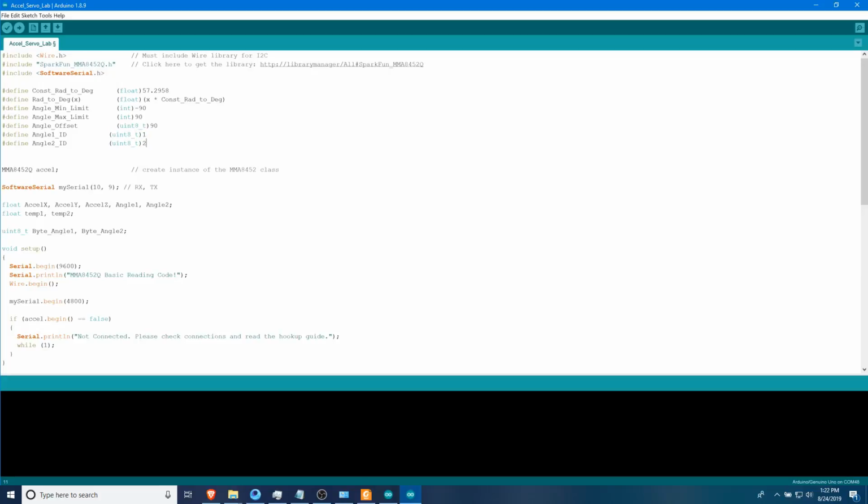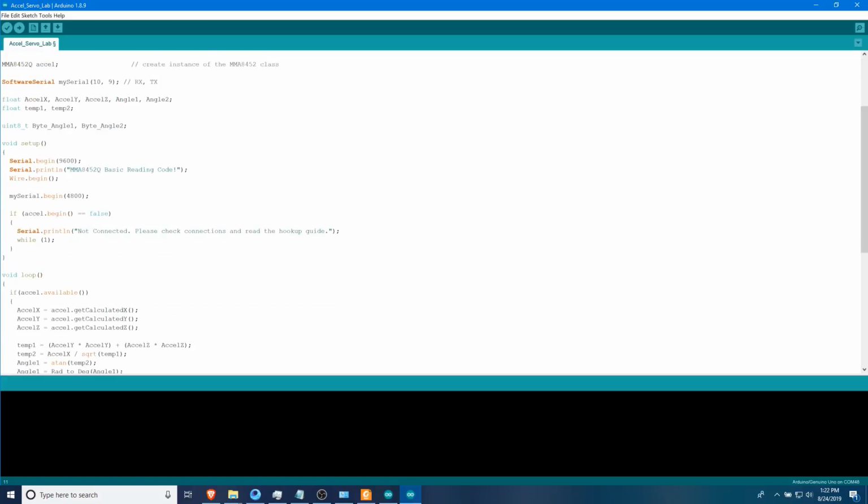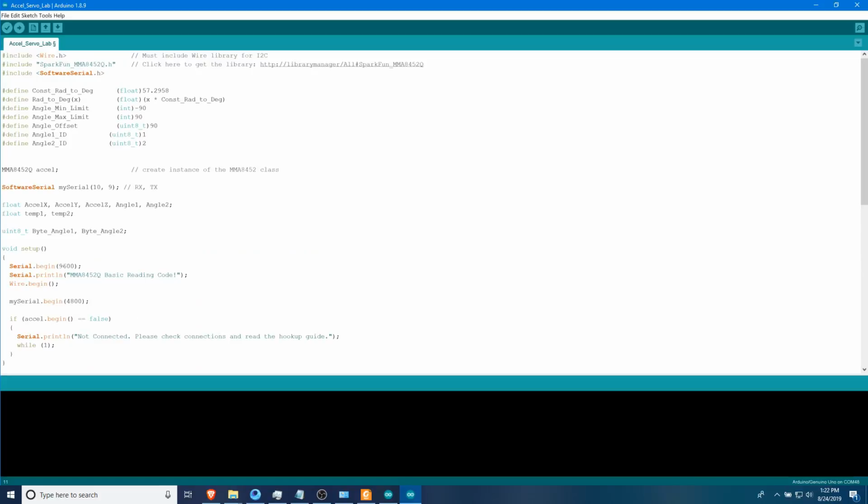So always remember, especially in the Arduino, that if you are using something and you are converting from one kind of variable to another, you have to have it typecasted. If you are using any constant values anywhere, you have to typecast that as well. You just have to. It's not a choice even, because the compiler of Arduino is somewhat tricky, and at times it just gives you incorrect answers for not having the typecast.